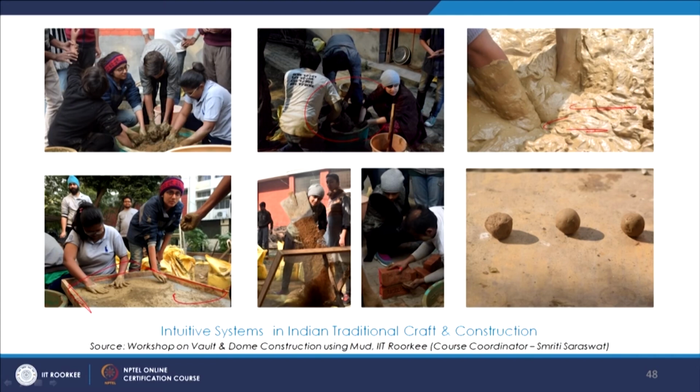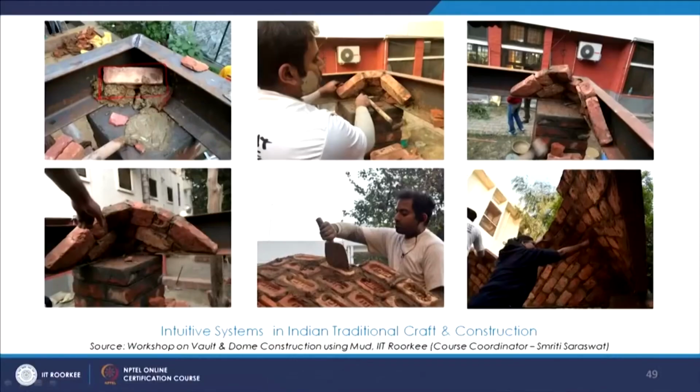Also, testing the bricks for testing the mud mortar for adhesion and load bearing capacity using the bricks, creating samples in different ratio to learn and understand which one is more stable, which one would expand and crack, which one would stay for long. And then starting from the first step after the mud mortar is ready, how we start from the first brick and how in steps we try to get this dome going.